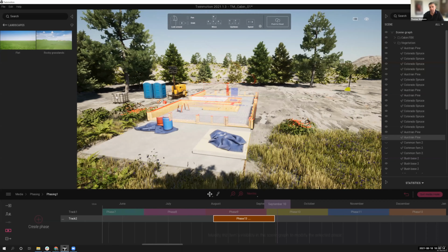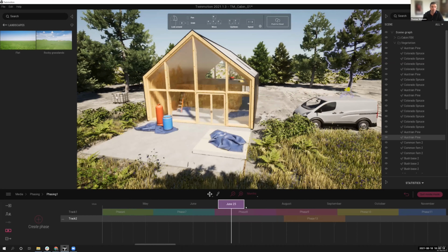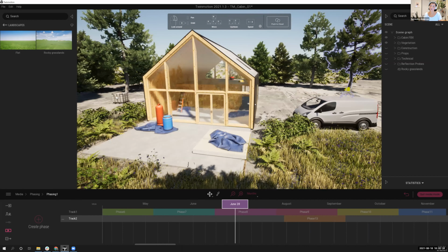Yes. Can the phasing be a link to layers? Because layers come in from Archicad, so could that be linked so that you're actually using the layers or object components like that? Yes. So if you do your layers in Archicad, when you bring in your model from the very beginning, you'll want to choose keep hierarchy, which is one of the import options that you have. The other option will get all your materials and put them together. But if your layers are created with materials, then that's fine as well. But yeah, if you have your layers set up in Archicad, you can come over here and set up the phasing to turn off and on for layers as well.